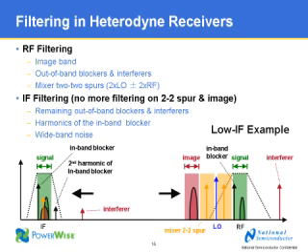And in addition to that, you'll see that the in-band blocker now, the second harmonic of it, that's generated by the IF amplifiers, is now much closer to the IF band of interest as well. So again, filtering that second order harmonic becomes more difficult as you go into the low IF architecture. So I guess just to be clear in this analysis, you talked about the second and the third harmonic. I guess in this example, the third harmonic is just so much higher frequency. Yeah, we didn't mention it because really the bottleneck ends up being the second order harmonic of the in-band blocker.